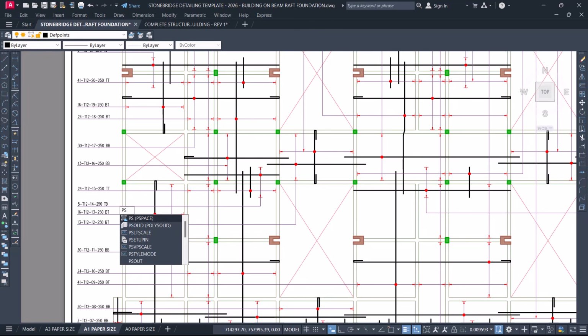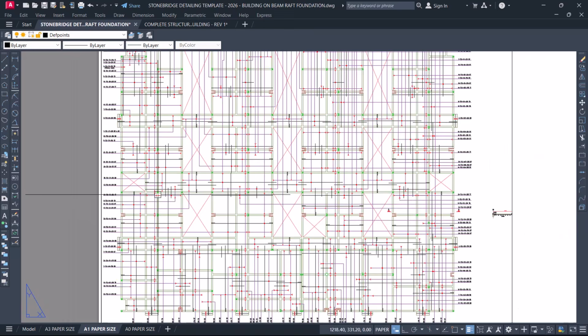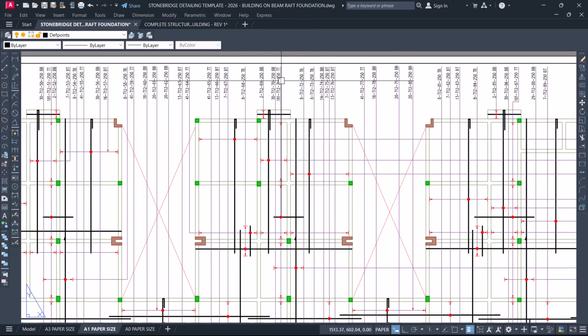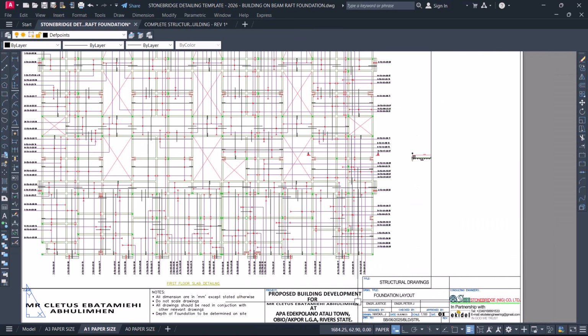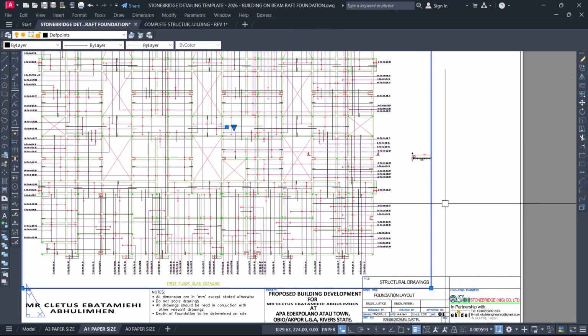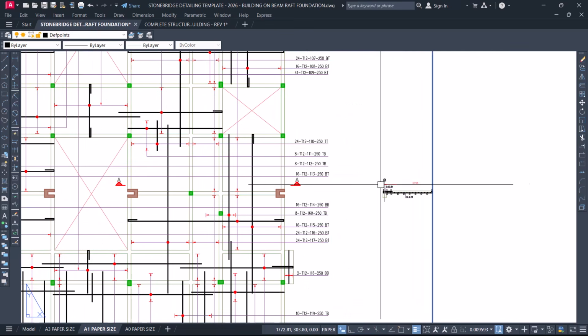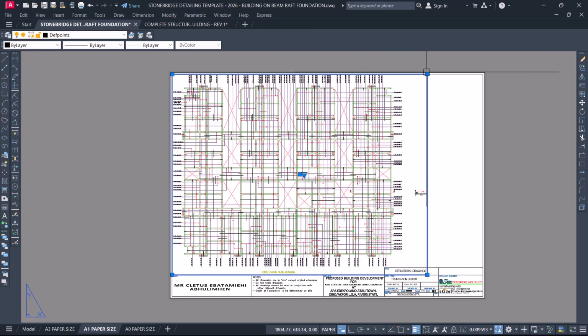Now you can see that I can choose to reduce my viewport backward. I can reduce it just to avoid this other section that is here from showing. So I will cut it like this by holding here, with my snap on, my auto key, to keep the line straight, and then stop it here. Correct. So right now our viewport is hosting only our slab.